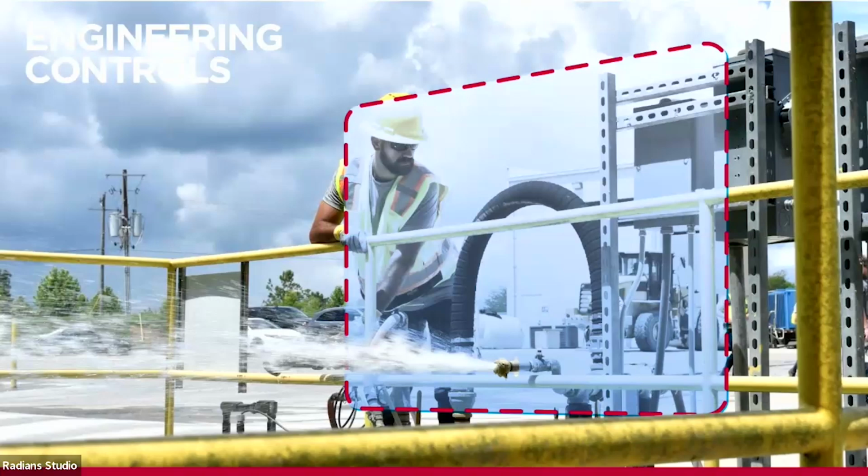OSHA is going to come on site. They're going to look at that and go, hey, you did right. And again, as a former safety director, anytime OSHA was happy, you were happy. All right. You weren't getting a fine. But they would look at that and say that is an engineer control. You want to make sure. Now, your signage there would say, stand behind plexiglass shield before turning on the valve. You know, you'd give instructions there. But that's where they would be protected.